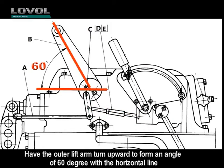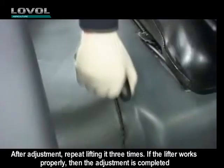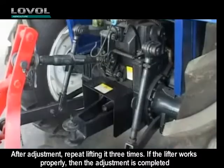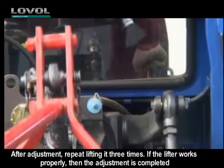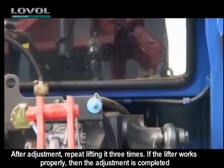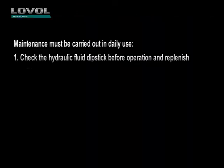Have the outer lift arm turn upward to form an angle of 60 degrees with a horizontal line. After adjustment, repeat lifting it 3 times. If the lifter works properly, then the adjustment is completed.